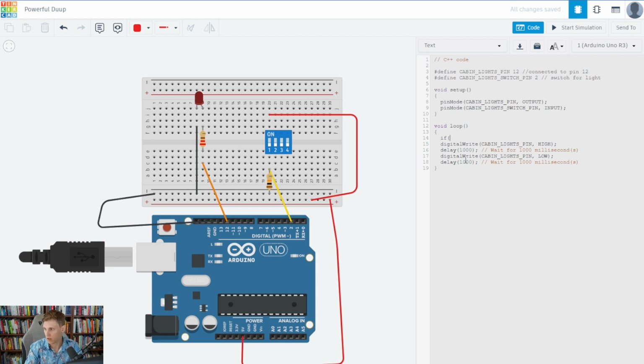Well, if we can use the new function digitalRead, which is for inputs. So digitalWrite is for outputs. It's writing a signal to an output pin. digitalRead is reading from an input pin. It's reading the signal that's being sent on the pin. So digitalRead is used for inputs. digitalWrite is used for outputs. But essentially they act pretty similar.